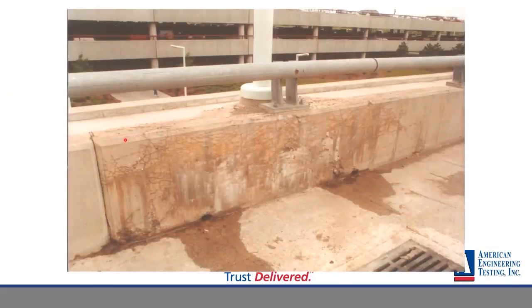So here's a real life photo of what alkali-silica reactivity looks like in the field. Those classic characteristic cracking patterns. All that white you see is gel pouring out of those cracks. So it can be really destructive.